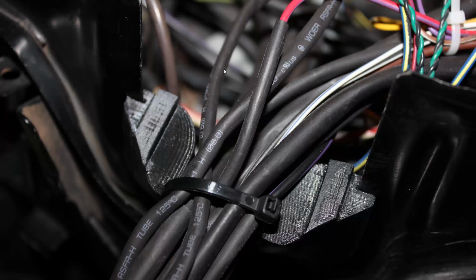So here's the bottom half installed. You can see I've hammered it into place. On the left and the right-hand sides, you can kind of see how this fits in. The firewall is only 50 thousandths of an inch thick, and so I made a slot in my part that was about 55 thousandths. I probably should have given myself a little bit more room. I made my part straight across, and it obviously fit, but I feel like this firewall had a little bit of a curve to it. And so that's the reason why I had to hammer it in. But I didn't break anything. It seems to be working fine right now, but we'll see how it stands up to the vibration.